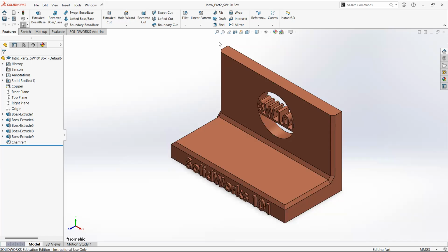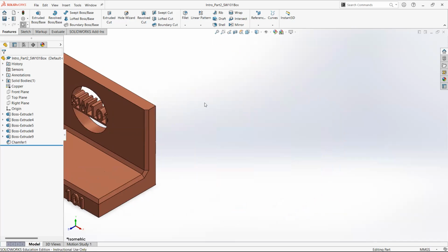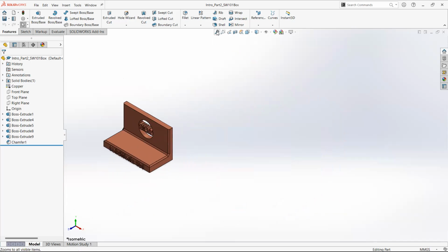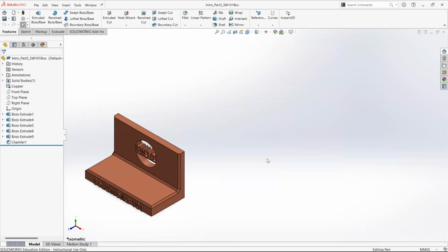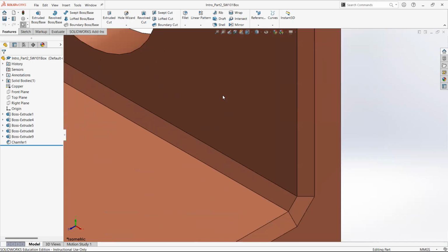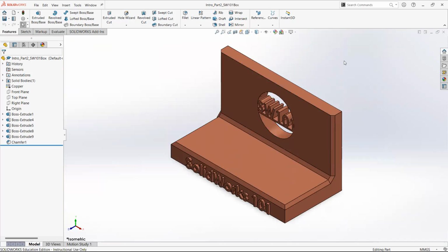And from here, those are the main buttons of the mouse, and we will be going to the navigation bar on SolidWorks at the top. So we have zoom to fit. If, for example, we pan and we zoom out, by clicking zoom to fit, SolidWorks will change the view so that the part will take the full screen and it will be the center of the screen. So again, if we move somewhere else and we zoom in or out, we click zoom to fit and we'll have the part in the center of the screen.